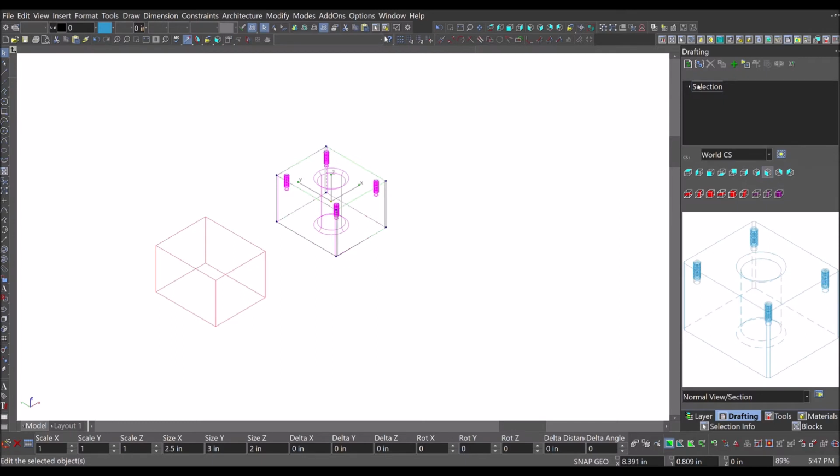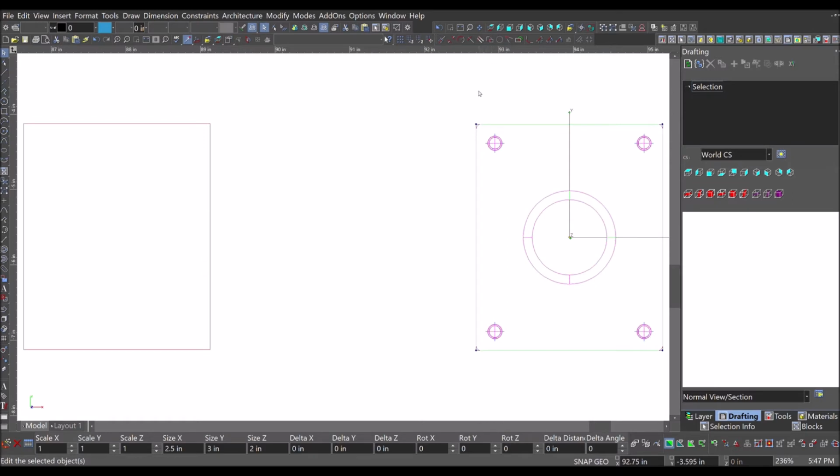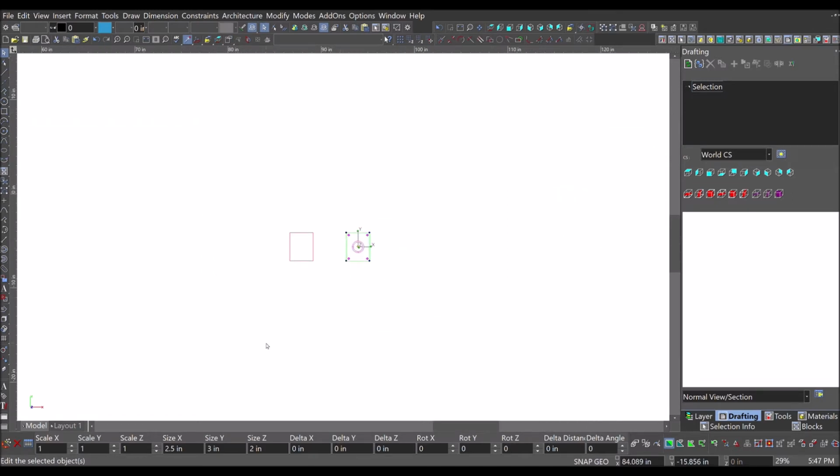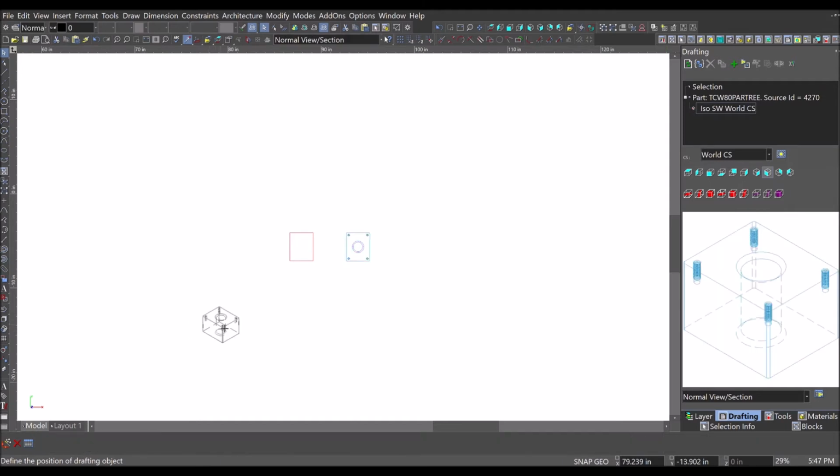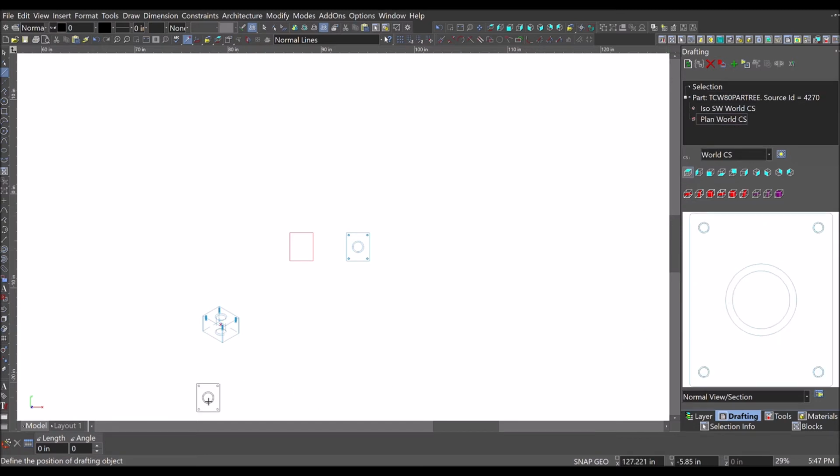As I open the drafting palette, again, you'll see some hesitation there. That's because I'm selecting the coordinate system, the entity coordinate system. I always select world because otherwise it gets confusing. It depends on who drew the part, what particular coordinate system they were using. If I go by world, that's a kind of a given. Everybody has a world, so I always make sure that that's selected.